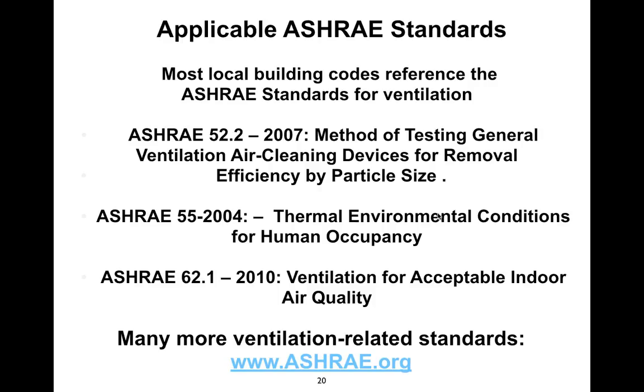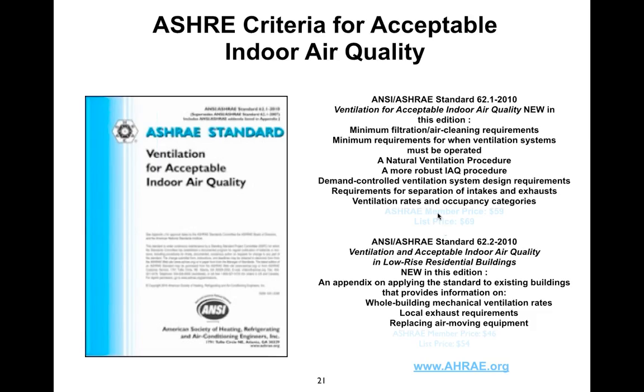62-1 is ventilation rates in buildings, air movement, how much fresh outside air you should have, and so on and so forth. And this ASHRAE standard in 1970 permitted much lower levels of exchange with outside air than it does today. Notice this is the 2010 version I reference here. I think there might even be a more recent one.